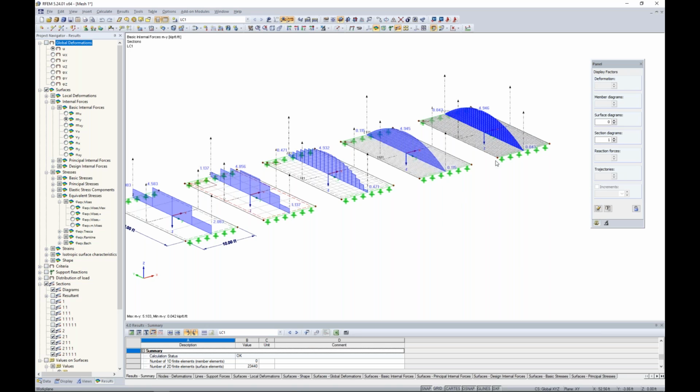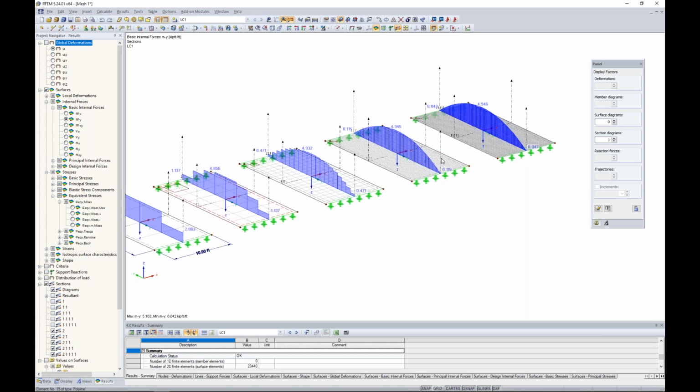So for example, these 2 elements here, the one on the left has about 1/3 the FE mesh than it does on the right, but yet our results are only changing by 0.001. So it's kind of this happy medium here to find out the right balance of when we are able to refine our FE mesh to gain accurate results, but not too much so that our calculation time is increasing significantly because we've added all these additional elements.